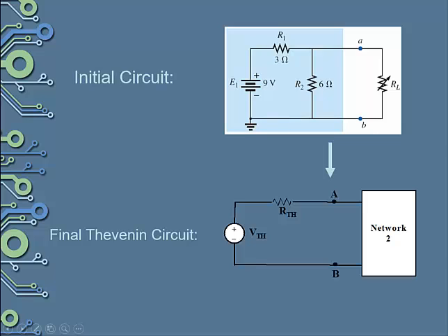So in summary, a few reasons when the Thevenin equivalence is useful is when you're required to analyse networks with sources that are not in series or parallel, to reduce the number of components required to establish the same characteristics at the output terminals, or when investigating the effect of changing a particular component on the behaviour of a network without having to actually analyse the entire network after each individual change.